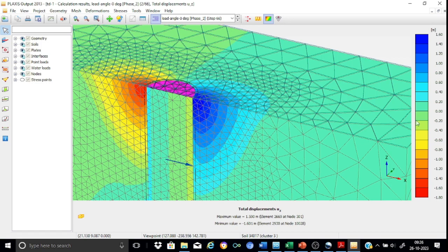The blue is a positive displacement, and on the other side we have got a negative displacement. That means on this left side, we have got an active case getting developed for the suction caisson, and here on the right side we have got something like a bulging of the soil, and that means development of a passive region, just like the case behind a retaining wall.